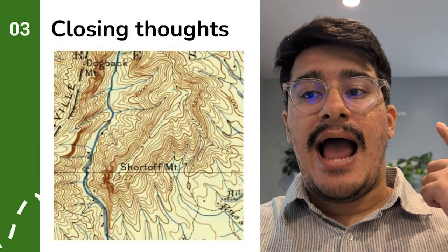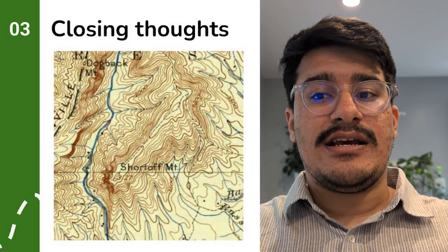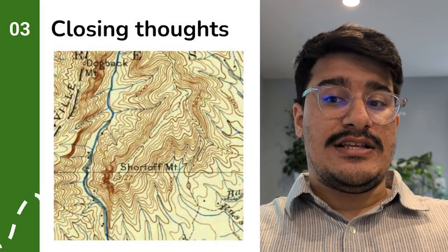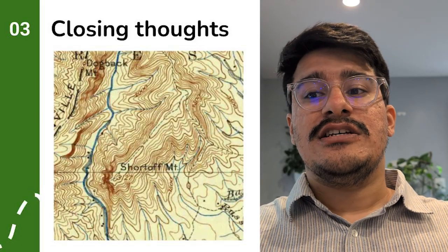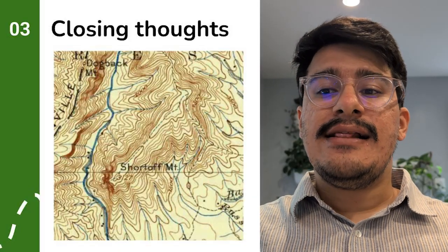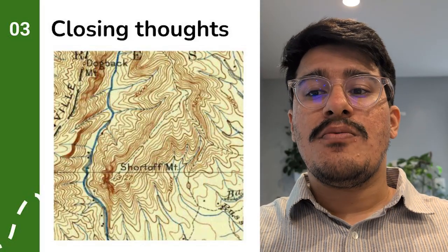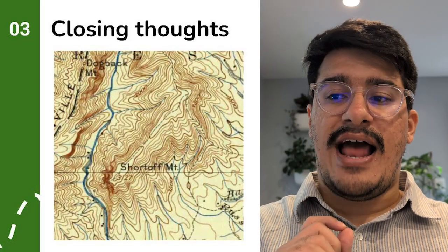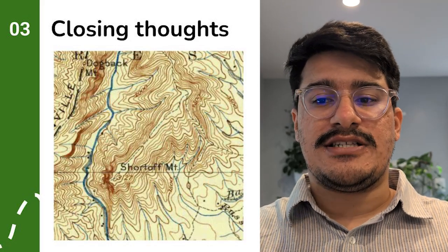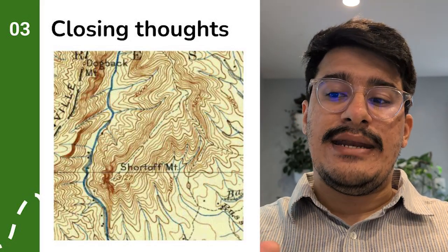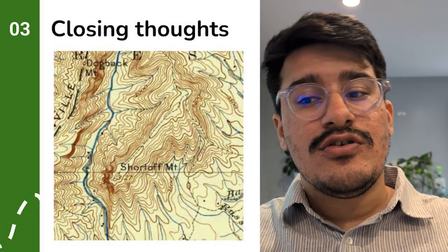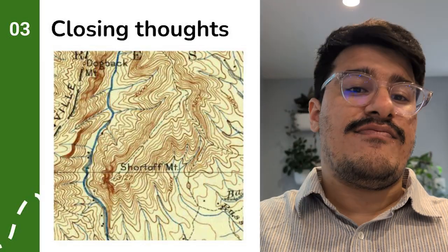Produce a map highlighting all areas above a critical threshold slope, showing, for example, that 30% of the site is off limits because it's steeper than 25% slope, or at the minimum, detail the range of slopes present through multiple sections, not a single value. It may say the site has areas ranging from 10 to 40% slope with an average of 22%, but then the regulation will still disallow using any of those areas that exceed 25% slope.